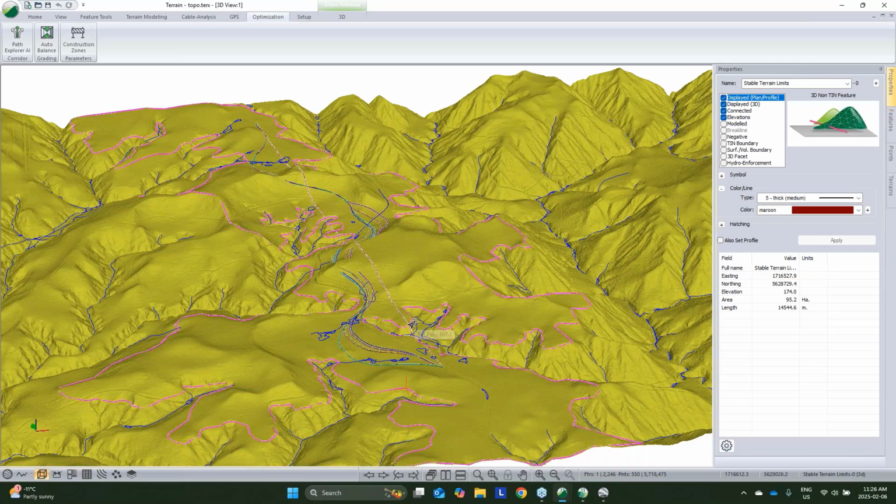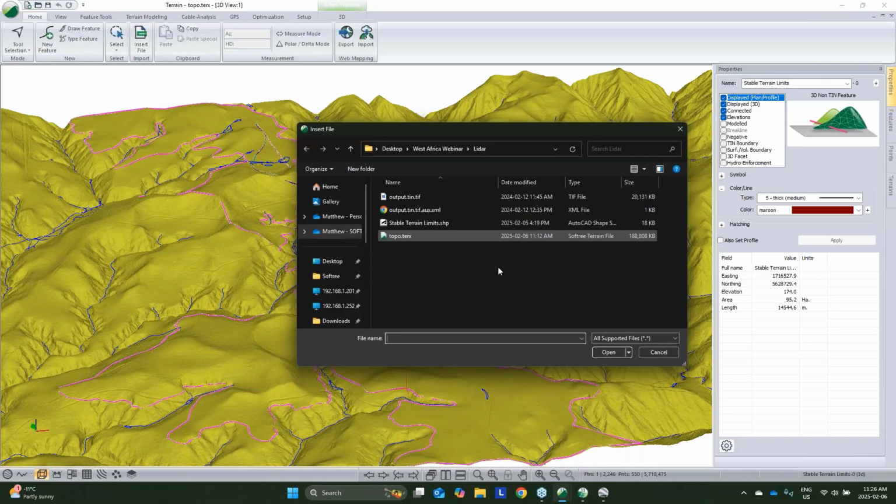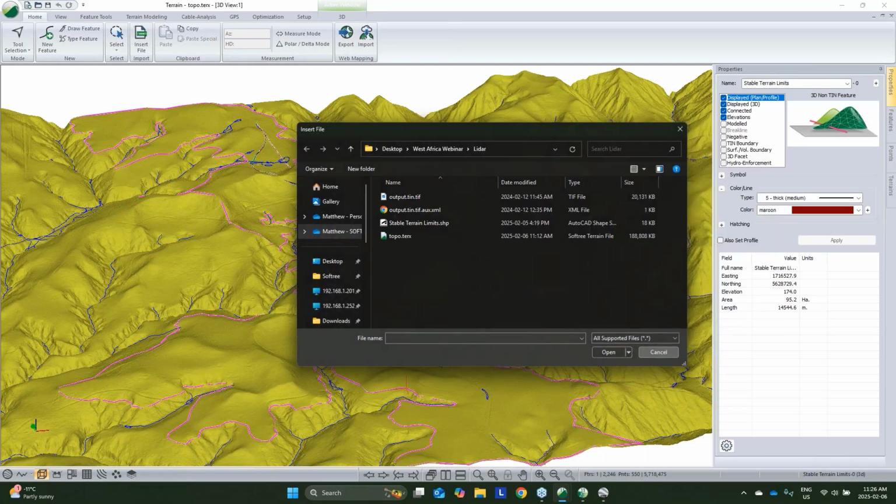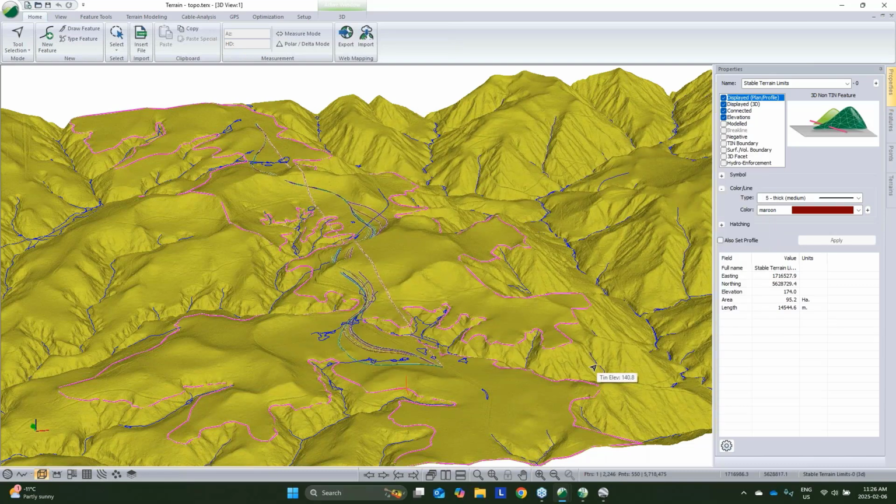And yeah, there's all sorts of times where you want to use that data from another source. So it really is just a matter of clicking insert file, and we can see there's a bunch of supported formats just with the default settings. GIS, though, shape is going to be the big one. You can bring in imagery data as common image formats, but TIFF is probably the most common one. So could be orthos, could be something that you've got mapped as just a graphic for something else.